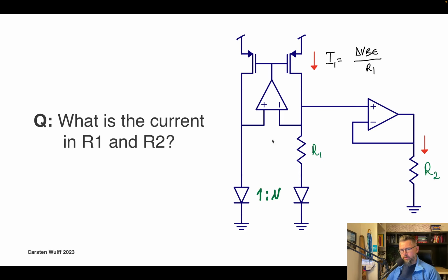But to get to how the low voltage band gap works, we use the same circuit. Now we know that the voltage at the top of R1 here is the same as the diode voltage. And in this picture, I've used a unity gain buffer to put that across a resistor. So what we know is that the current that flows through this branch and through this resistor actually has to increase with temperature, because I've said the voltage across this R1 is proportional to temperature.